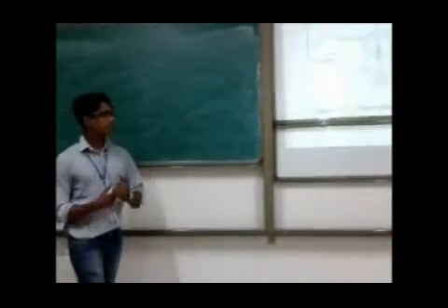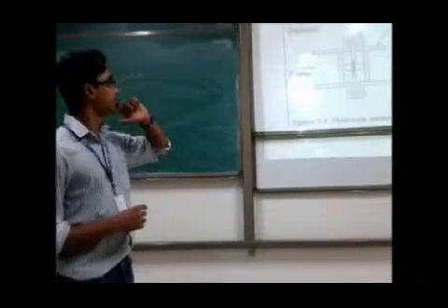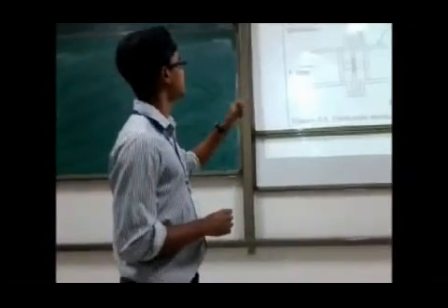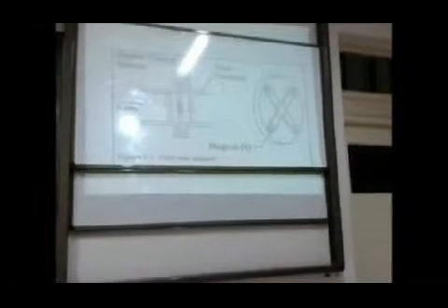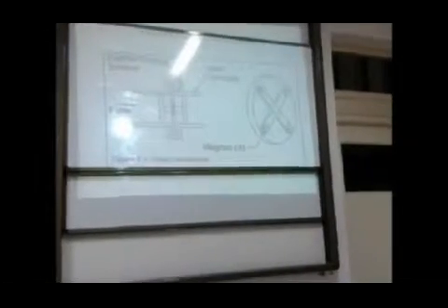Next one is flow rate sensor. Actually, the flow rate sensor consists of a digital output sensor through which the water is going to flow, and a magnet which is used for sensing the flow of water. This figure shows the concept: it uses a digital output bipolar sensor, and the magnet is mounted to an impeller to measure the flow rate for a water softener.